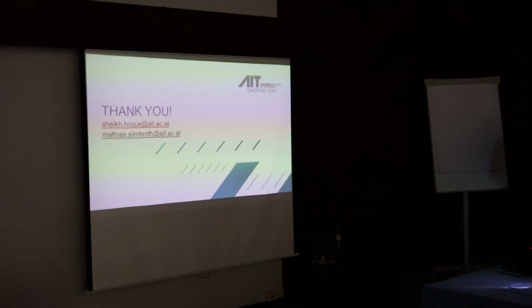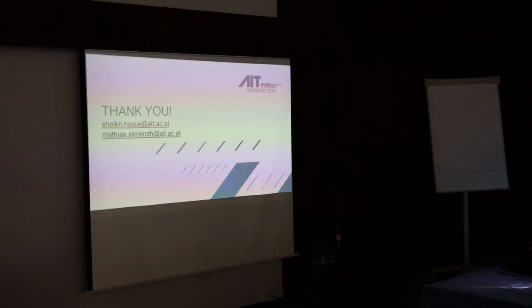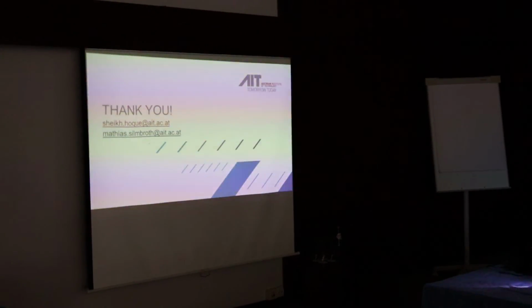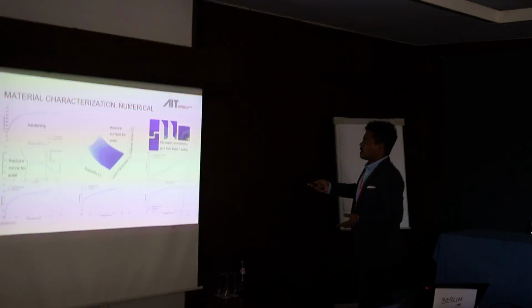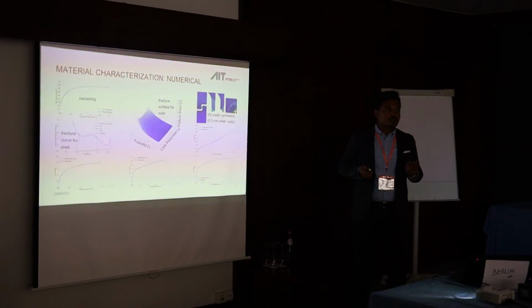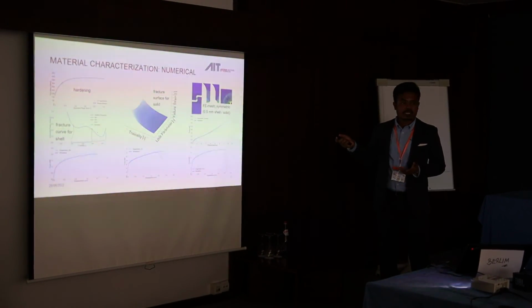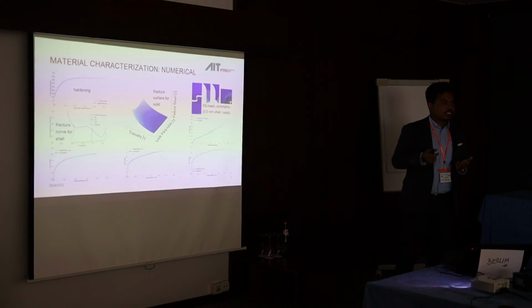The parameters for your damage model were determined from experimental characterization. Yes, exactly, because this is what I have shown here. These are the specimen tests to calibrate the damage model. You do not get the parameters directly from the experiments because it's a shear test, and the strain is not really the failure strain under shear. The strain path is not straight, not linear, it deviates.